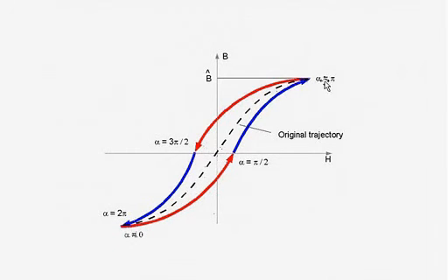The only caveat is, if you had a DC bias, you could not do that. You would have to solve with the DC bias and with the full cycle. So anybody designing, for example, a choke that's a DC smoothing choke would have to use a little bit more elaborate solving method than what I'm illustrating today. So I only solved a quarter cycle, and the results in the spreadsheet show that.